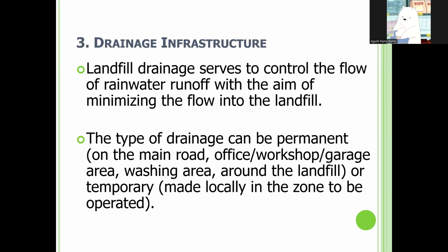So the third is drainage infrastructure. So the landfill drainage serves to control the flow of rainwater runoff with the aim of minimizing the flow into the landfill. And the type of drainage can be permanent on the main road, office, or workshop or garage area, washing area around the landfill, or maybe can be temporary or made locally in the zone to be operated.